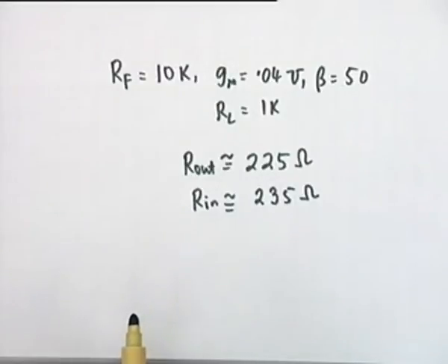This low value of the input and output impedances is very important, as you shall see when you use overall feedback or you use more than one stage of feedback. Then the matching between the preceding stage and the succeeding stage will require that you use series succeeding shunt. If the output is a shunt connection, then the matching will require a series connection at the input, so that the input impedance is much larger.